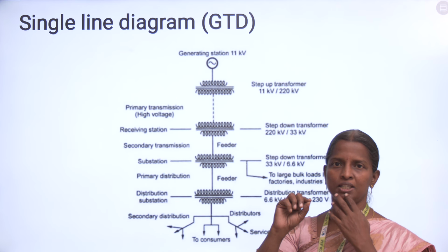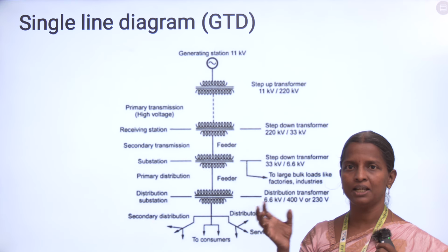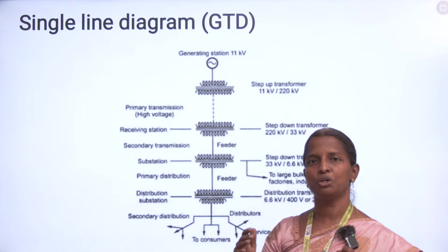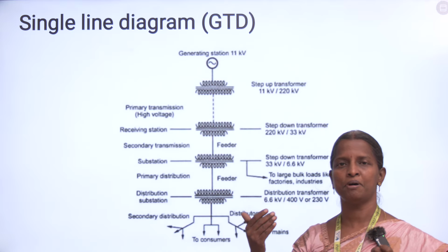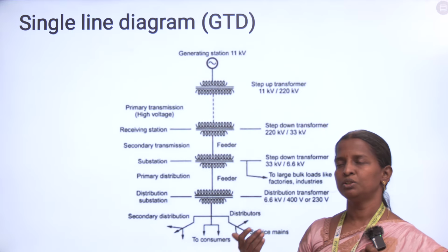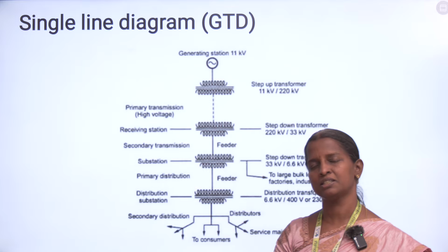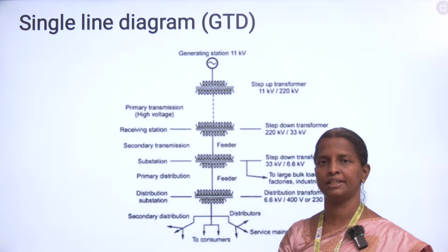So at that point, what is the intensity because of that current flowing? It is called magnetic field intensity. H is equal to Ni by L, that is, mmf by length. So those are the three main parameters. What are the three main parameters? Magnetic flux, magnetic flux density, and magnetic field intensity.